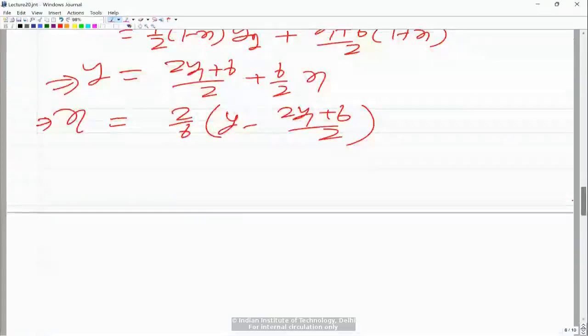So first we have to find out the corresponding xi and eta coordinates, and once we know the xi and eta coordinates, then we can calculate the shape functions at that point, and then using the nodal values we can calculate the variable at that point through summation, and similarly their gradients.